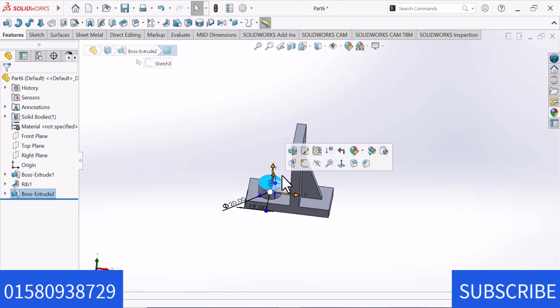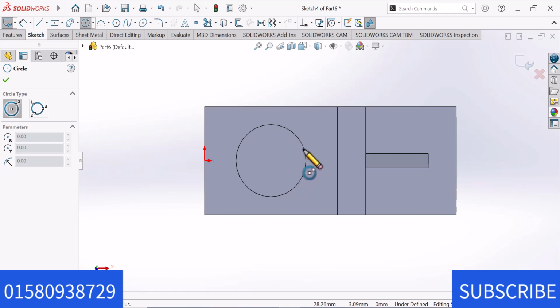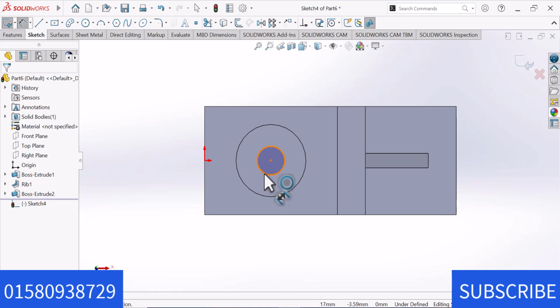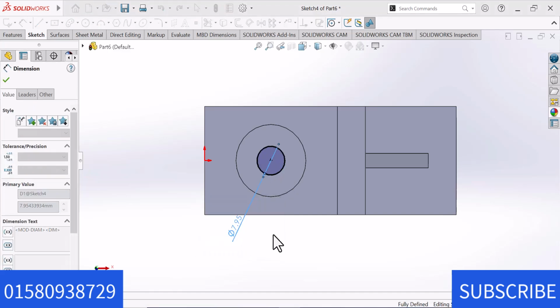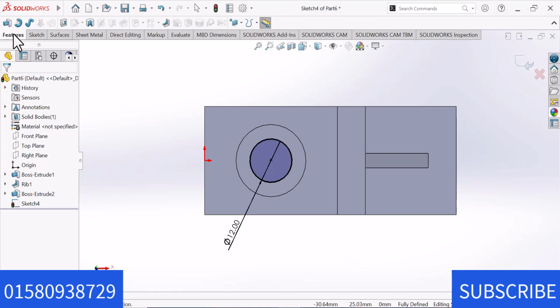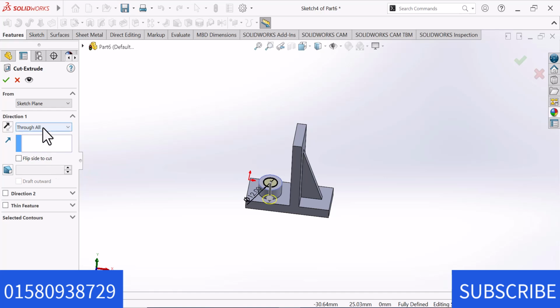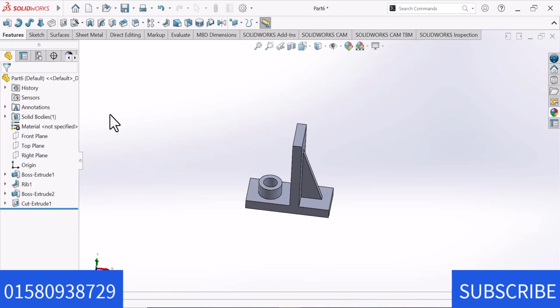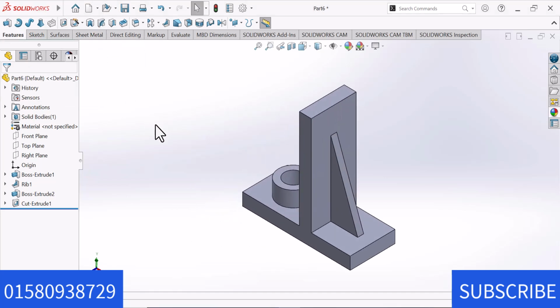Now this face and sketch. Now draw the circle here. Give the circle value 12, and go to Feature and select Extruded Cut. Now here cut extrude through all. Now go to isometric view. Now we have made our job.